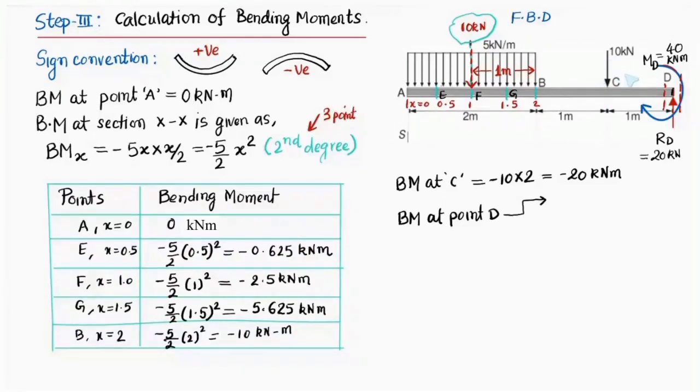Similarly, during shear forces also, if there is a point load acting, we will be considering before the point load and after the point load, so that when we say just left of the point, we will not consider the load, and when we go just right of the point, then we will consider the load in case of shear forces. So this is a very important understanding.